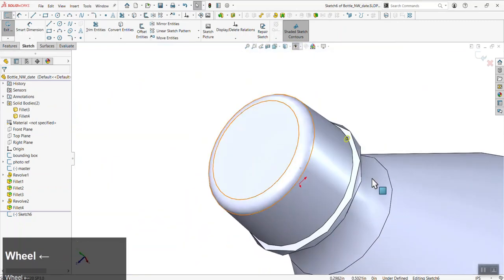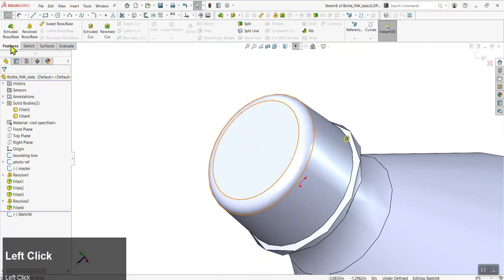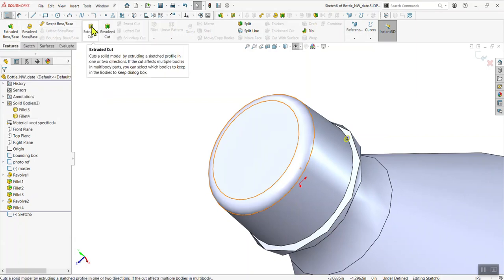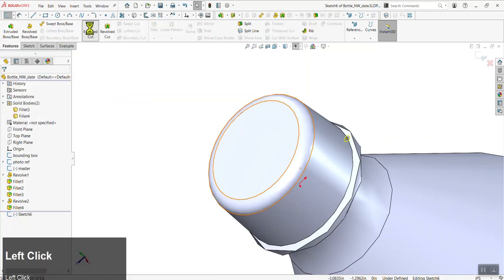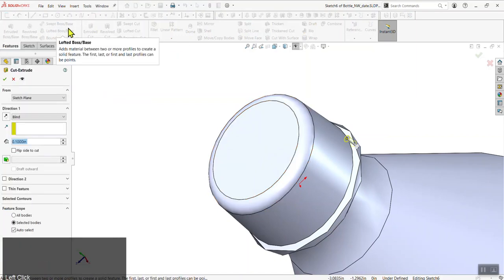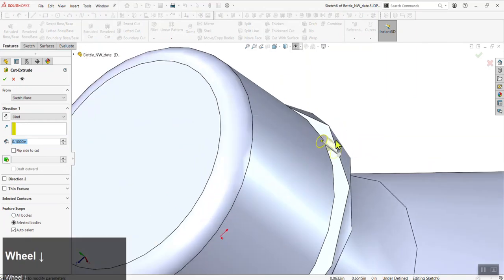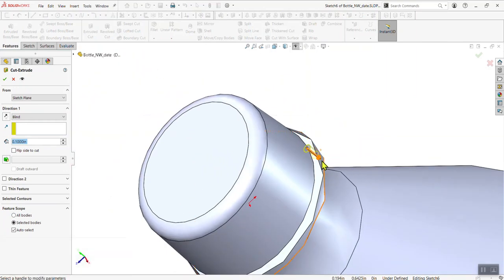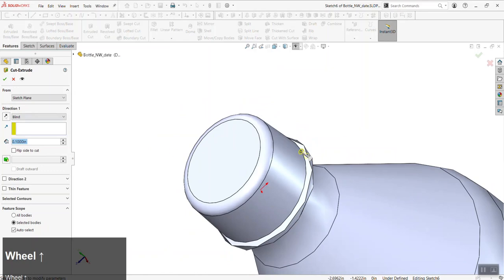So now we're going to introduce the new feature. While we're still in the sketch, we can go back to the Feature tab. And again, everyone's cap is different. You may have sort of an extruded grip. Again, mine's a cut grip. So I'm going to go to Extruded Cut. These two features are similar. It uses the shape of the sketch to project it into space and either add material or remove material. But just take a tour of some of the properties here.